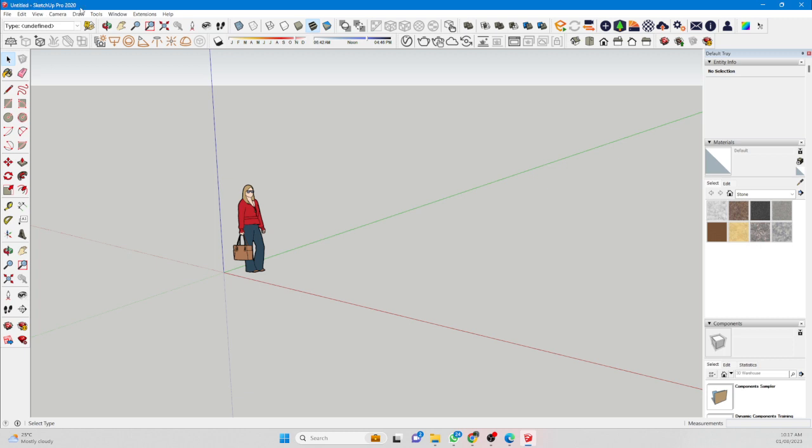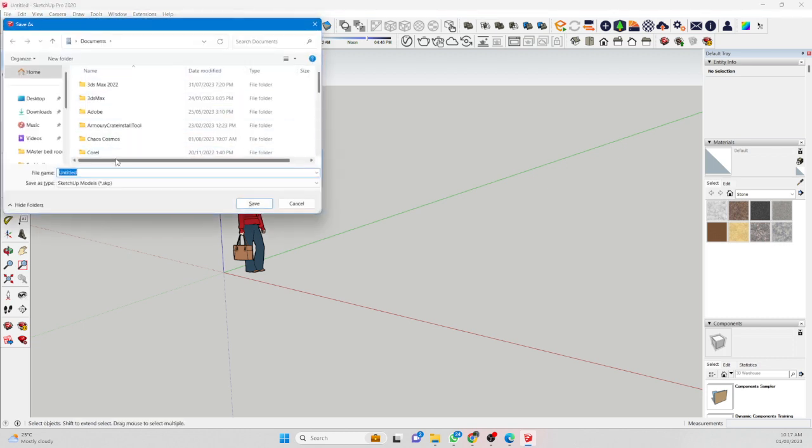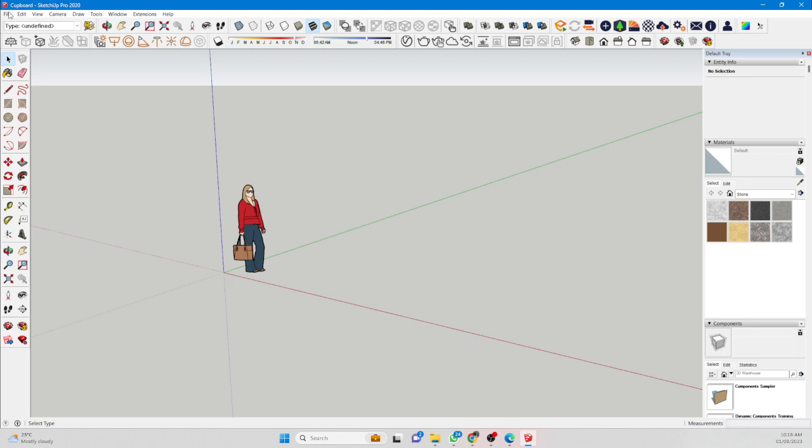We haven't saved any file right now. After we save with Control S and give the name, we'll make a cupboard. Then press enter, and see here: cupboard dash SketchUp Pro 2020. So first is the SketchUp logo, then the file name, and SketchUp Pro 2020.